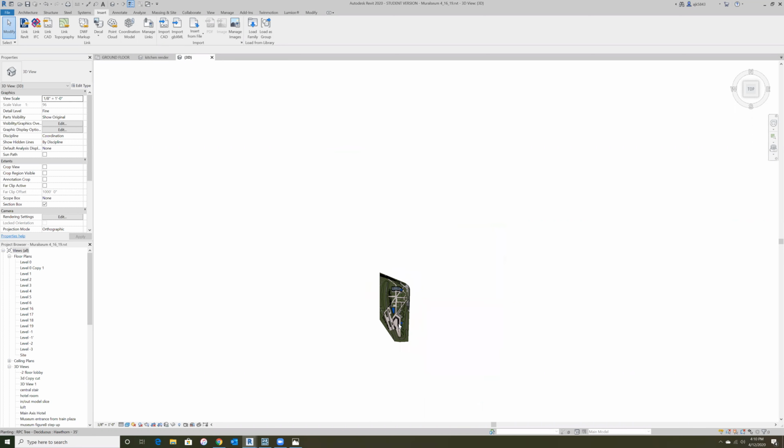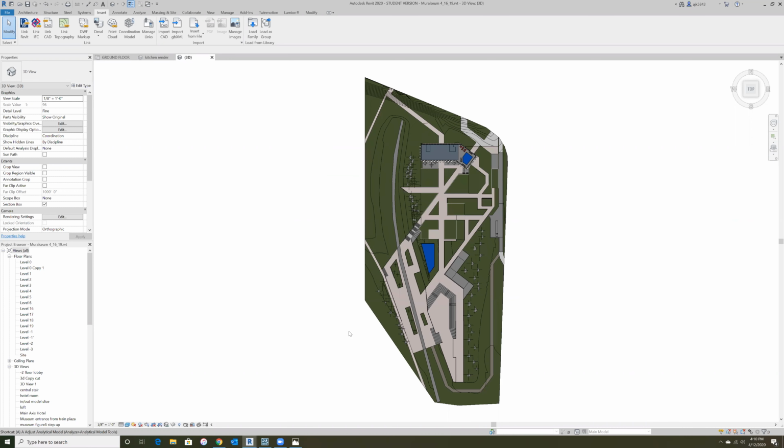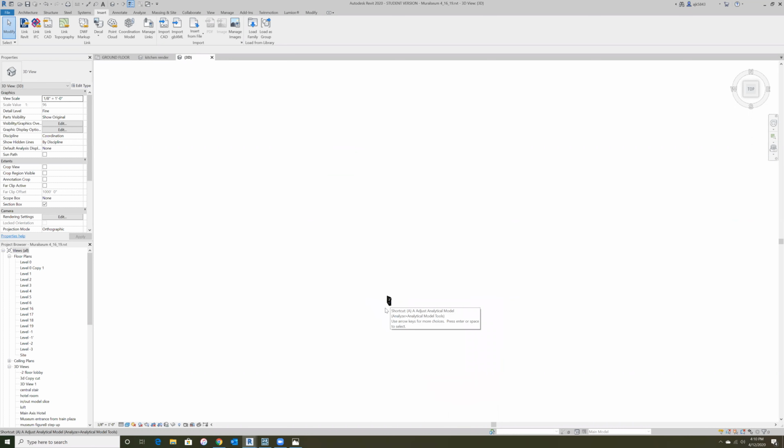You oftentimes have to find wherever Revit has decided to import the instance to. In this case, if I remember correctly, it is somewhere very, very far away. It will bring it in as a pinned object. So before you would go to move it, you would also need to unpin it to allow that to work.